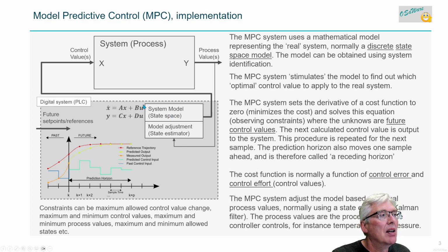That's my optimal criterion. And what do I have to do to achieve this? Zero error, no overshoot. Yeah, I get to zero error, but my process value went to 250% and my tank emptied or whatever, on its way towards zero error. So it's this u in the future I want to find.